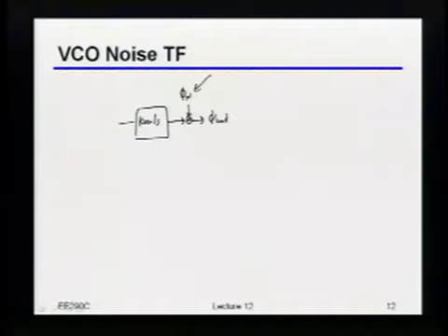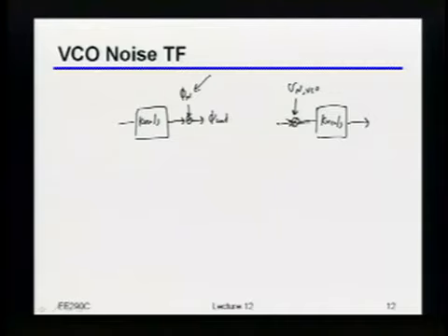So usually the way you'll model the VCO noise is instead to say, well, I know what's really happening is that I have some amount of thermal noise that I'm adding inside of the VCO, and then that's getting accumulated. So instead of trying to model the phase noise directly, why don't I model that as some voltage noise going into the VCO and then getting accumulated?